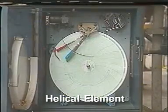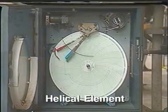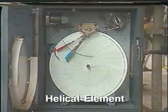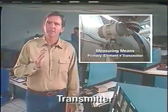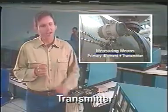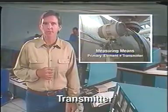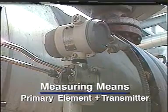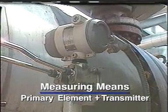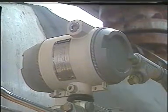Devices of this type are often called sensors or sensing elements because they change shape, size, or position whenever a process variable changes. Transmitters are another group of instruments. A transmitter gets information from a primary element or sensor and then transmits a measurement signal. Either electricity or compressed air is generally used to transmit these signals. So when we talk about a measuring means, we're usually talking about a primary element or sensor coupled with a transmitter. This is an example of a field-mounted transmitter that transmits flow rate measurements.